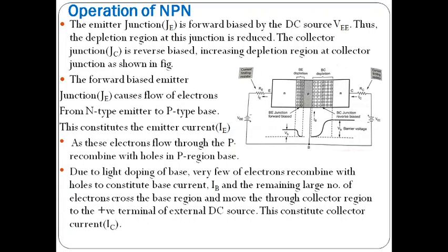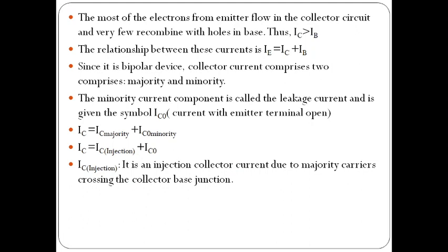It is a very small amount of current. When the diode is in reverse bias, we will get the minority charge carrier current. It is very small. Yes. So ultimately here you can observe the majority charge carrier current, that means electron current, and the minority charge carriers in the collector, or hole current. So here the total current is due to the electrons as well as holes in the BJT. So that's why it is a bipolar junction transistor.